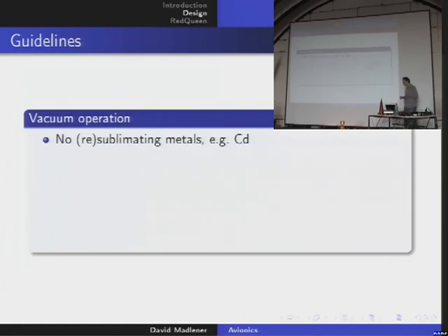And for example, at ESA, before you come as a payload specialist to insert anything in their computers, in their avionics, they explicitly check the connectors if there is any cadmium on it, and they give you special certified connectors that are absolutely cadmium-free as an interface, okay? Because they are really, really aware of the problem that any amount, be it just a milligram of cadmium in the system, could ruin avionics in vacuum.